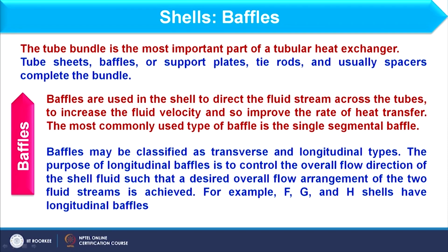So, in that case what have you observed? You have seen that baffles are placed along the length, okay. So, that is basically the longitudinal position, fine. And when I am considering baffles as a support plate to hold the tubes and to direct the fluid on the shell side, we usually arrange that in a transverse way, okay, which is perpendicular to the tubes, right. So, these are basically two positions for the baffles.